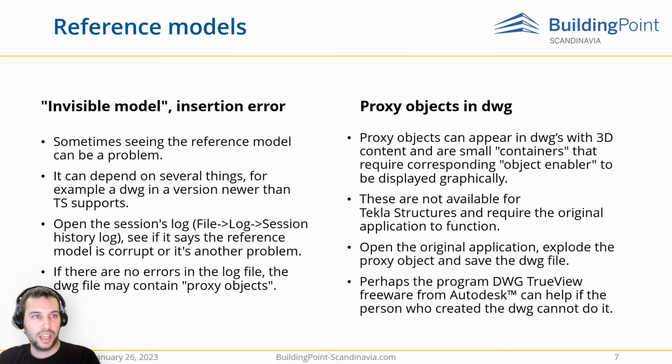Next up, again, reference models. Who hasn't encountered an invisible model when inserting it? It can be several issues. One thing in particular, it could be a DWG file that has a newer version than Tekla supports at this current time.